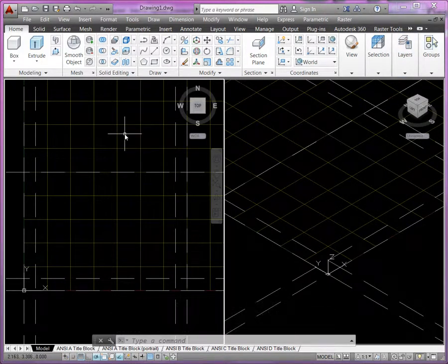And now, again, I'm going to use another 2D tool, right? Either Polyline, or you could use lines, or you could even trim these construction lines, okay? But the reason why I'm using a Polyline is because I can make a closed loop, okay? As a closed loop, I don't have to use a region. But if I have just collections of lines, right, then I have to make a region. So here, if I just use Polyline,